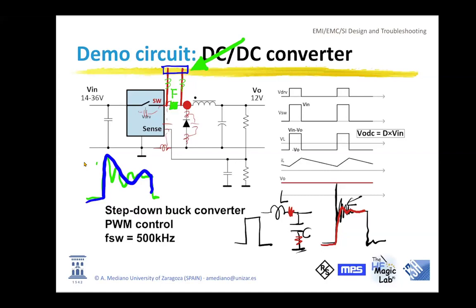If you look at the evaluation board information, you will see that they are using 4 layers with a good layout of the ground planes. And additionally, they have good decoupling capacitors, high frequency capacitors for filtering the activity. And additionally, they have introduced filters in the output cable. So this is the secret of EMI.